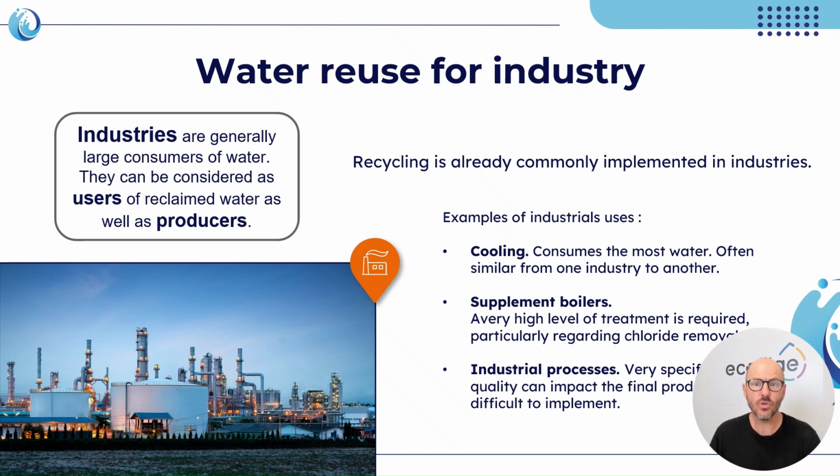Water reuse for cooling purposes is the most common use because it generally consumes the most water. Moreover, cooling practices are often similar from one industry to another, so examples and guidance are easier to find, making it easier to implement such projects. Reclaimed water is also often used to supplement boilers, although a very high level of treatment is generally required, particularly regarding chloride removal to avoid deposits and damage to equipment.